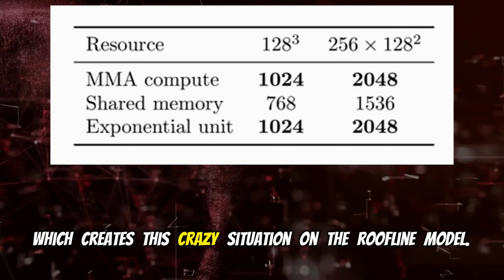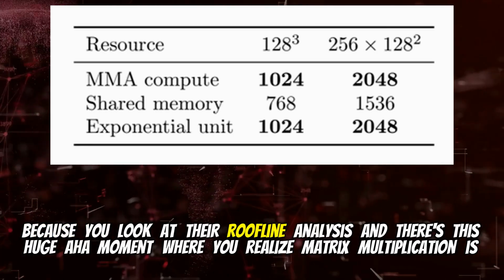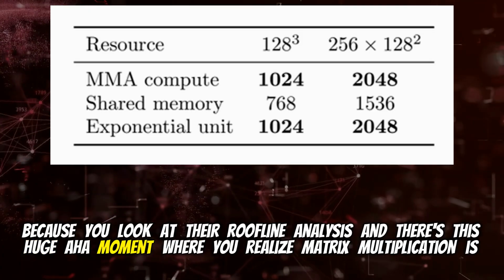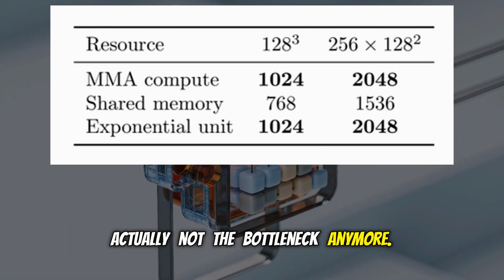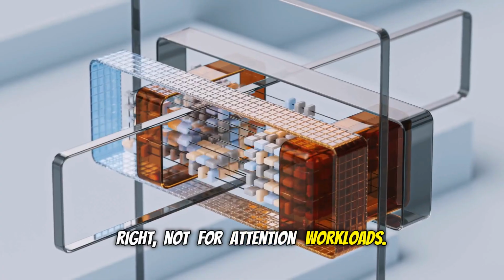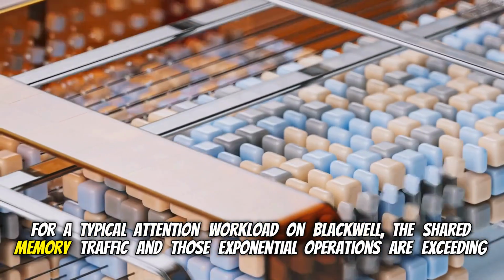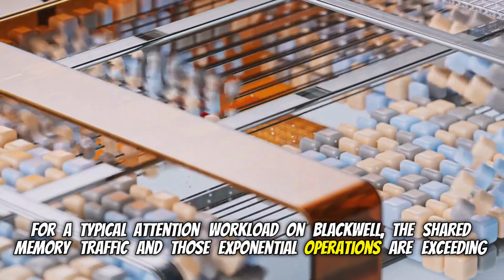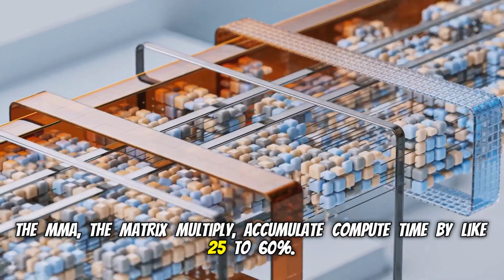Which creates this crazy situation on the roofline model, because in their roofline analysis there's this huge aha moment where you realize matrix multiplication is actually not the bottleneck anymore. Not for attention workloads. For a typical attention workload on Blackwell, the shared memory traffic and those exponential operations are exceeding the MMA, the matrix multiply accumulate compute time, by like 25 to 60%.